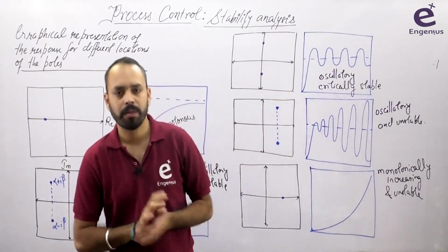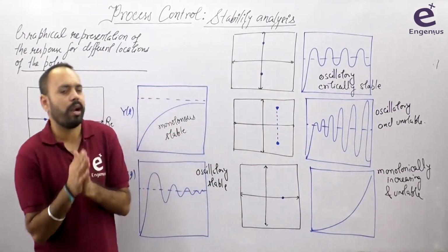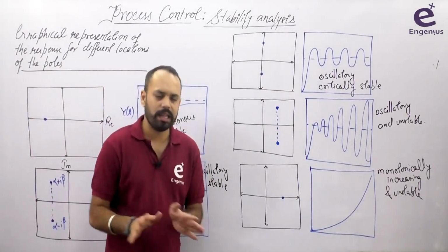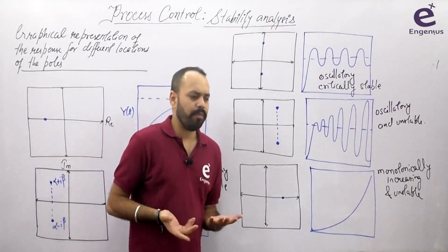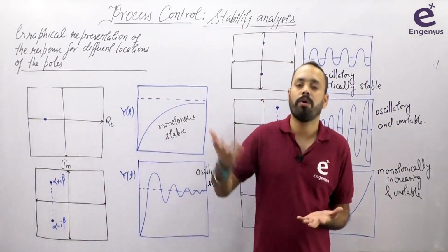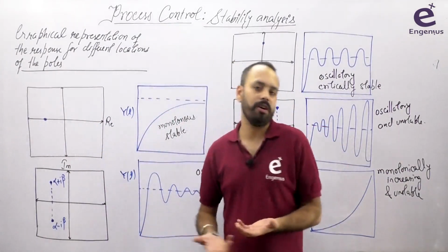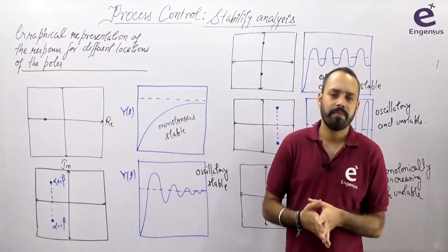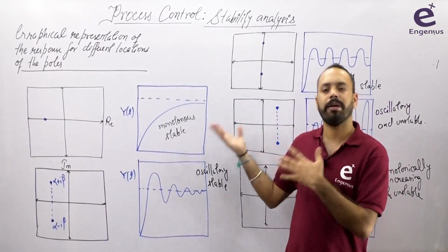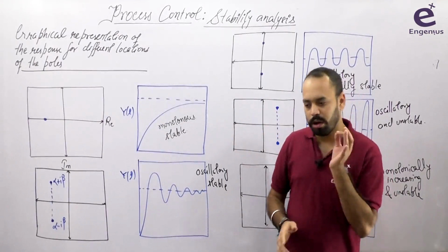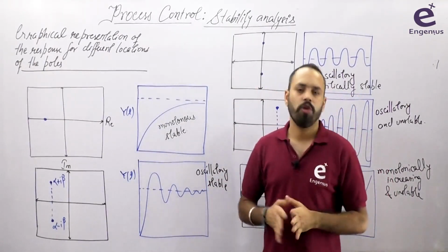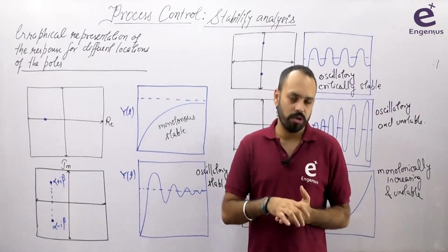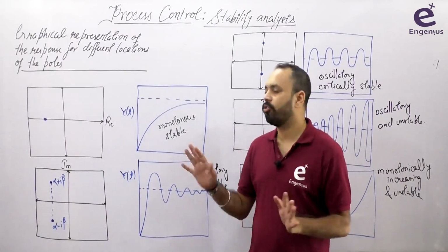Now here comes the problem. Sometimes the denominator is a quadratic or cubic equation, which is easy to solve, and you can find the roots and then you can comment about the stability. But sometimes the denominator can be 6th power of s, or even if it is 4th power of s, finding the exact roots of the solution takes time. It means, अभी तक, whatever method I have discussed here, if you want to comment about the stability of the system, you must know the poles of the transfer function. Without finding the poles, we can't comment about the stability so far.